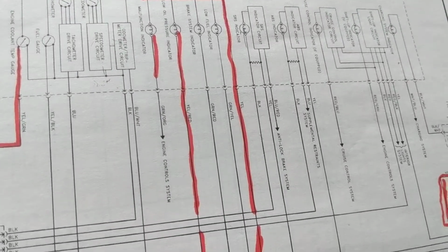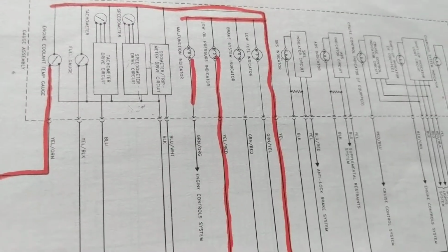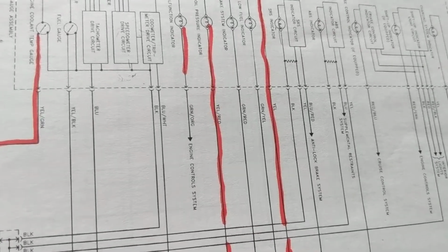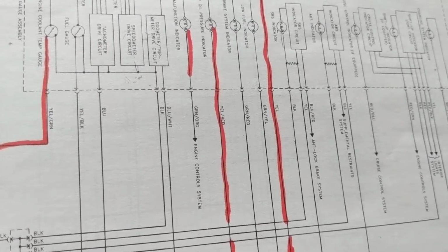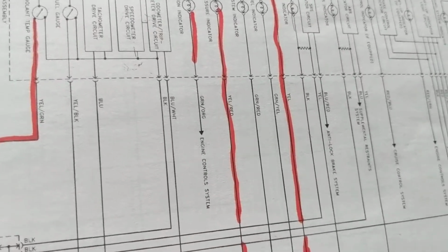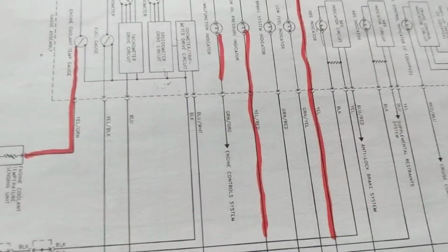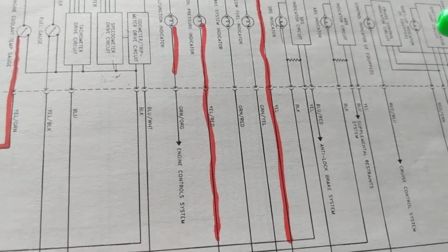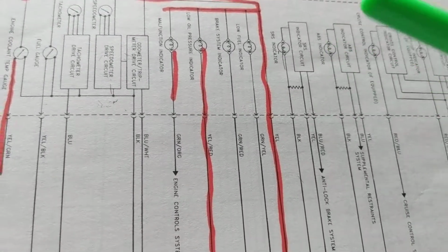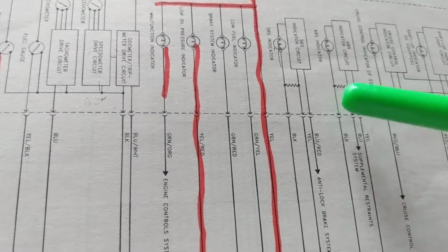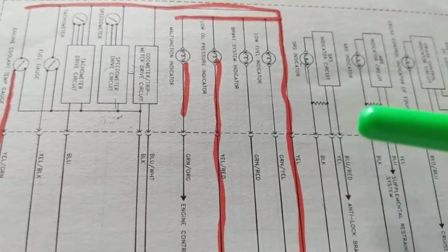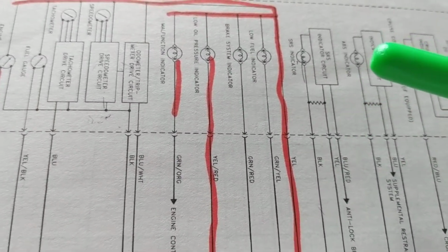Again, and a point to be made. I was talking about your car doesn't start. Besides the starter motor, besides the computer having control over the fuel pump, fuel injectors that we went over, ignition coils, if the camshaft or the crankshaft do not give signals that the engine is rotating, right, creating revolutions, that computer will shut down that car. Why? Because if the camshaft is not turning, the crankshaft is not turning, there's no purpose of putting fuel into the cylinders or a spark.